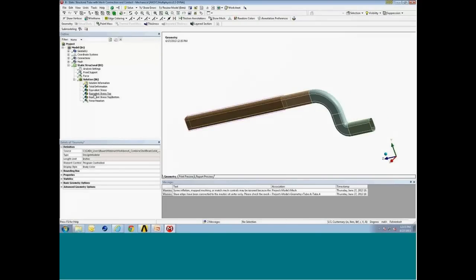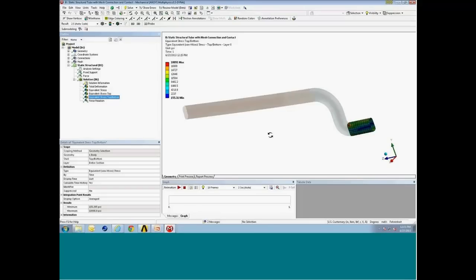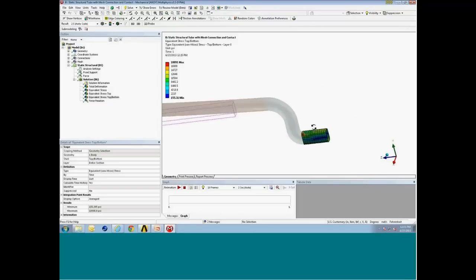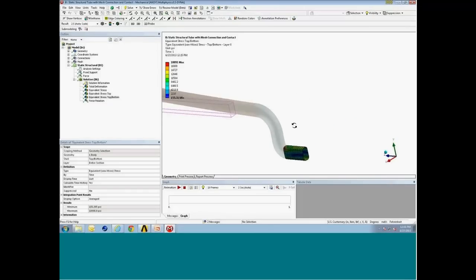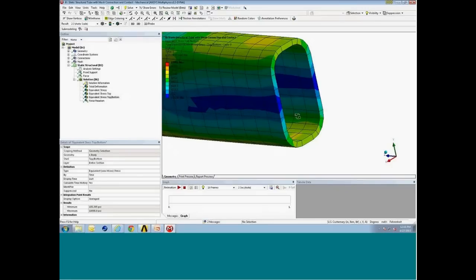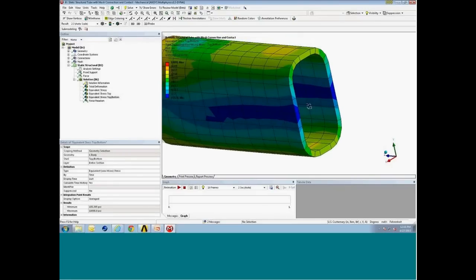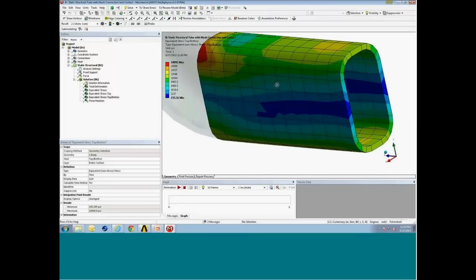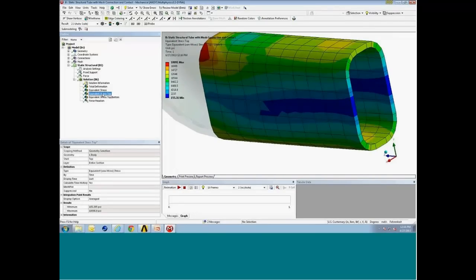And so when we look at stresses by default, we're looking at that when you view the top of the shell, it is the top surface stresses, and the bottom of the shell, that's bottom surface stresses. Let me turn back on our thick shells and beams here. So the visualization in mechanical does show a gradient through the thickness when you turn on the shell visualization. You can control just plotting whether you want the top only for the shell or the bottom only. You can control that with a pull-down menu. So you have that ability.